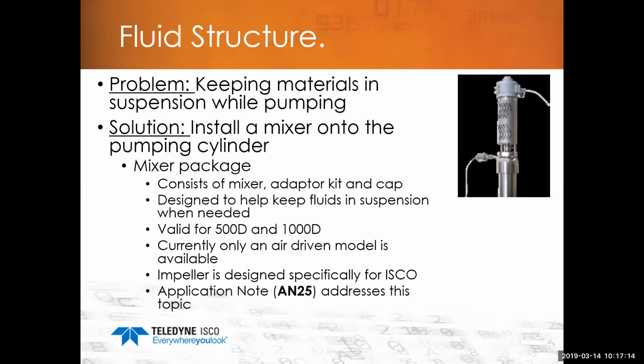Currently, it's an air motor, and in the short-term future there's an electric motor coming. So keep in mind when you're looking at a mixer like this, there may be some noise because you have an air motor driving it. But this is a perfect case if you have particulates in your fluid, or you need to keep the fluid stirring so it doesn't settle and stick at the bottom of the pump and cause pumping issues, which goes back to optimization.